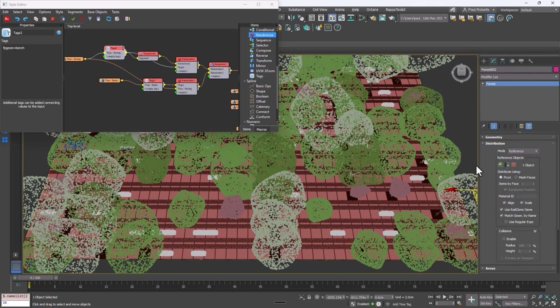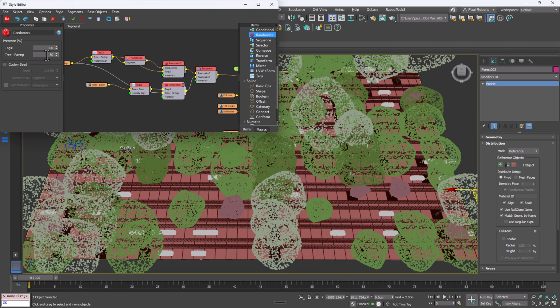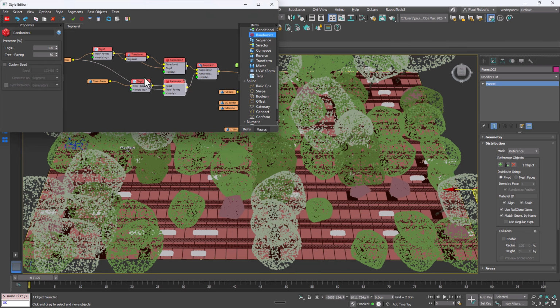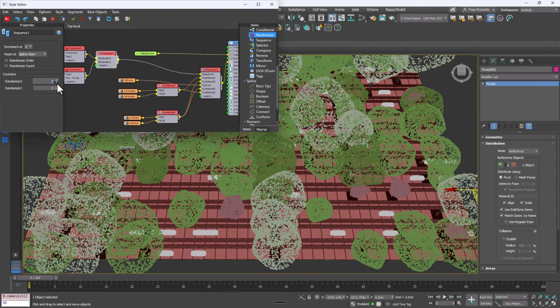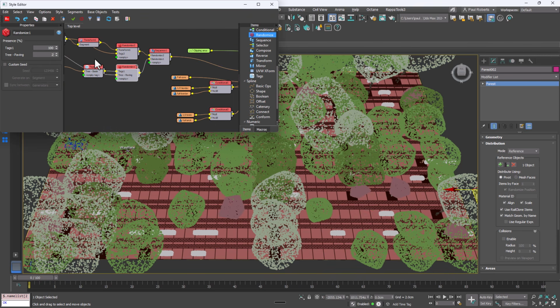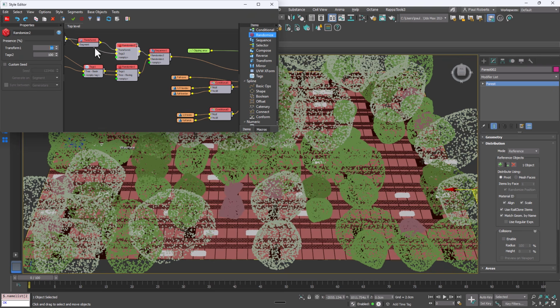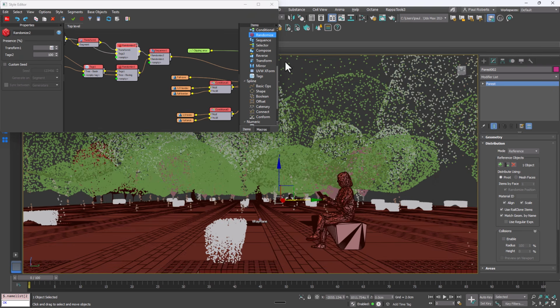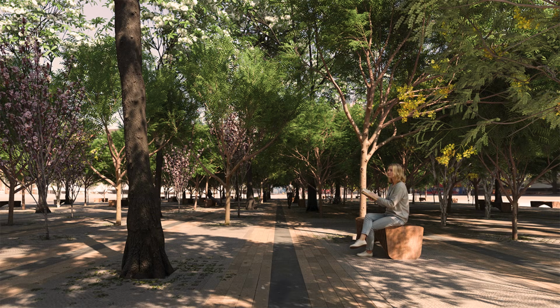RailClone handles the procedural paving layout and determines where different types of objects are allowed to appear. ForestPack then uses those exported positions to distribute the trees and the benches. And because the two plugins remain connected procedurally, you can continue editing the RailClone style, changing the paving pattern, the number of rows, the location of the tree basins, or the probability of bench positions, and the scatters will update to match.